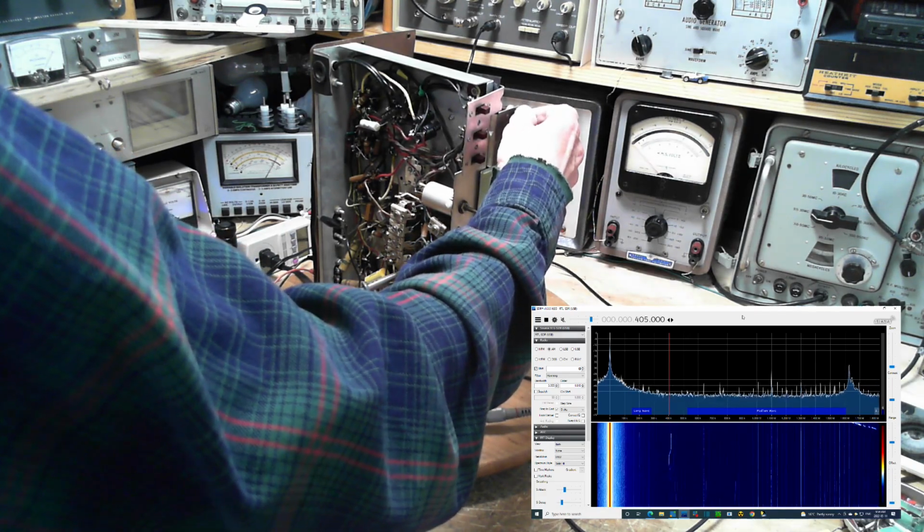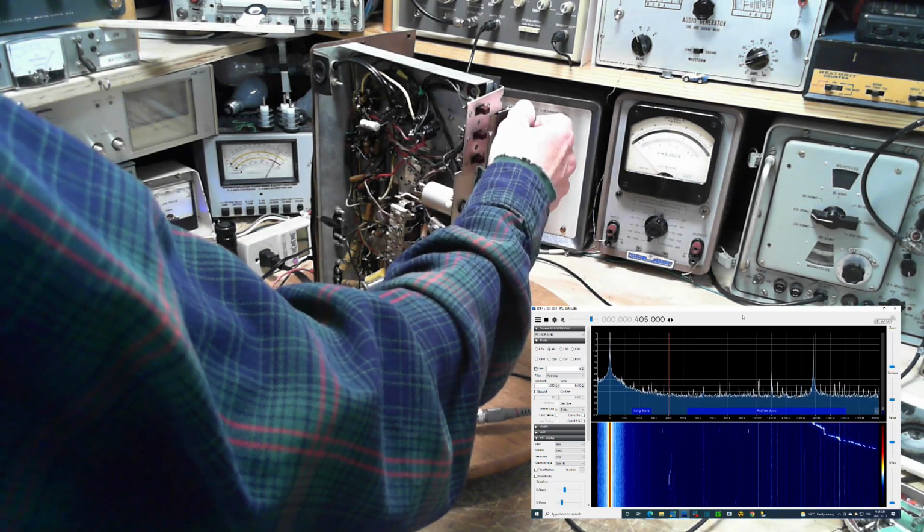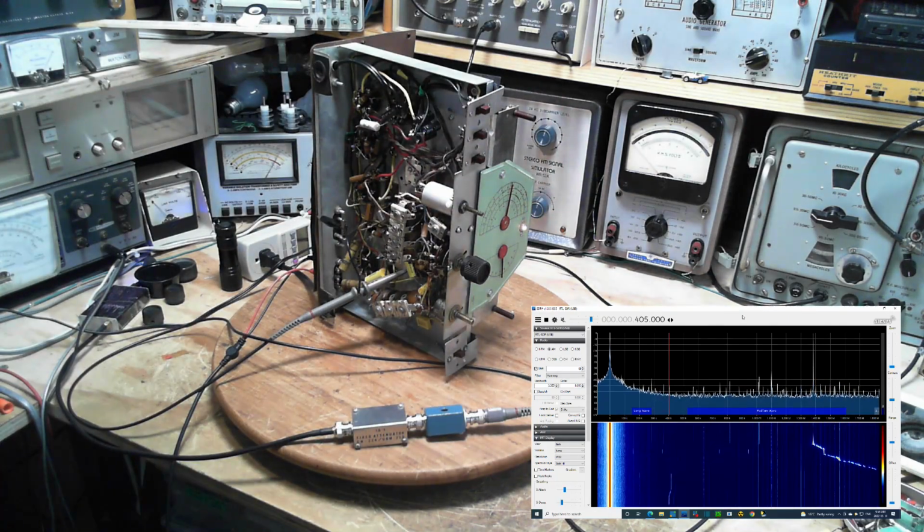So what this tells me is that the idea that the IF input resonance is going to result in the elimination or suppression, I guess is the right word, the suppression of all signals outside of 455. It's not very dramatic. You can still see a signal being converted by the local oscillator way far away from 455.